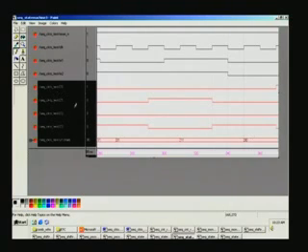Depending upon the state, that particular light also will go up. For example, Z1 is high here. That is because we are in the S1 state. That's what we want there, right? And here in the 1, 1 state, what happens? Say the clock is arriving here. Only at the positive edge of the clock will the transition be made. That's why it is extending here, right? So this will get reflected only later on.